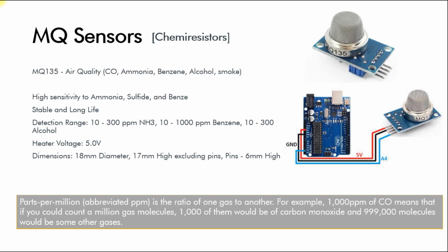One thing we should be very clear about: our Arduino UNO is only giving the data as a voltage waveform, so it is only giving a voltage value. It is also possible to convert the voltage value into ppm. There is a specific formula, some tedious calculation. If you apply the formula in your code, you can convert the availability of that particular gas, CO or ammonia or something, into ppm.